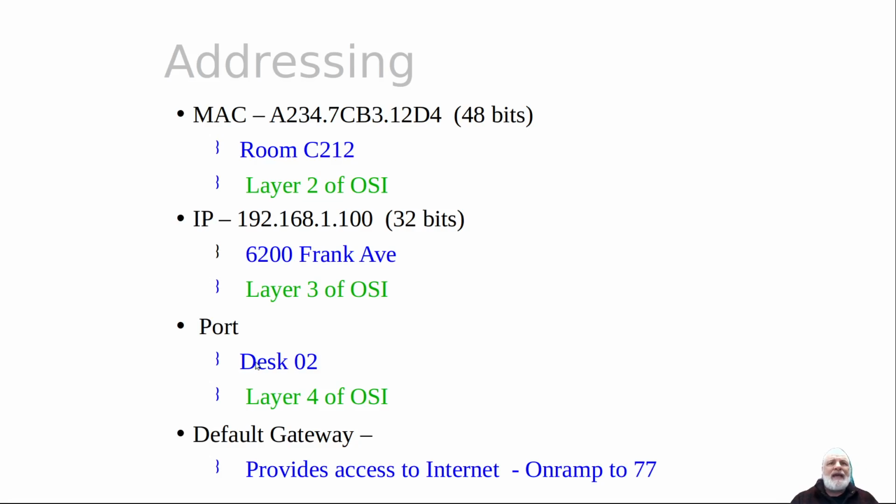Okay. And then we have the port. I already kind of discussed the port, right? Your IP address for our BeagleBone was 192.168.7.2. That was the BeagleBone. But then the port number was that :1880. Well, the number is the 1880. The colon's just a separator, right? But the 1880 after the colon gives us the port that got us into Node-RED, as opposed to some other service or server program running on that BeagleBone, of which there are actually several.